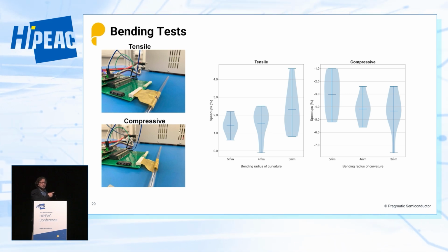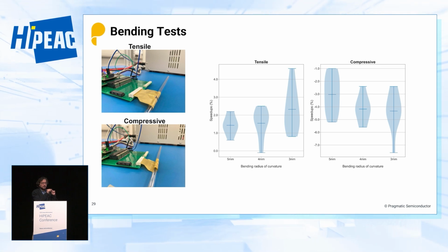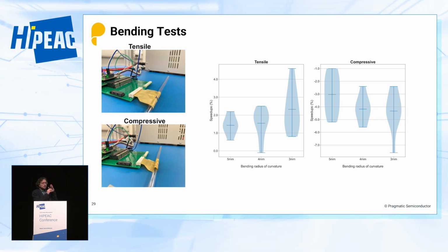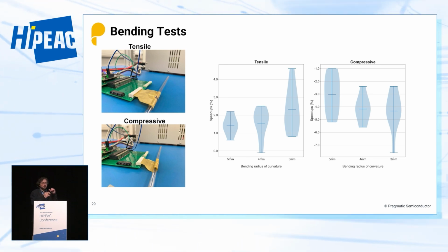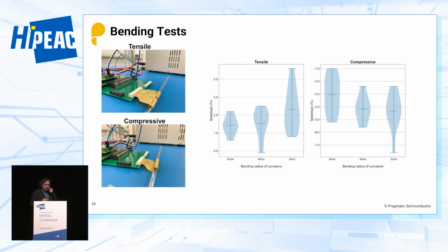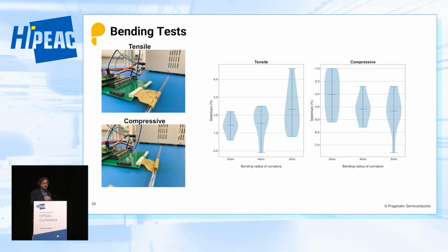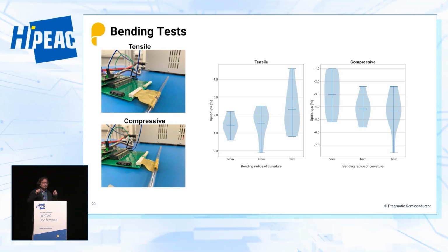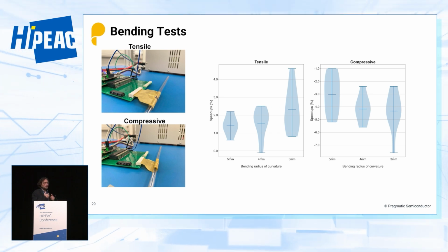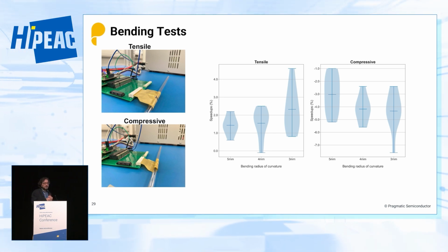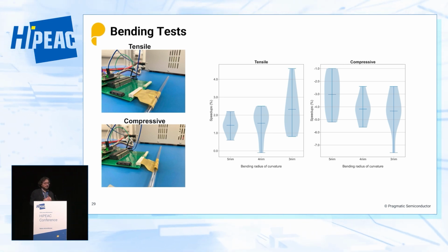I think at the transistor level, researchers have done this, taking one of the IGZO transistors, which is what we use. They do this bend test, and they see that the transistor mobility or the threshold voltage changes with the mechanical stress. But at the system level like this, it was the first time we have done this, and our tests were very rudimentary. Right? So we buy cylinders and then roll this PCB just to test. So there is more research that needs to be done to understand why this happens, and can we actually utilize this interesting phenomenon to speed up.